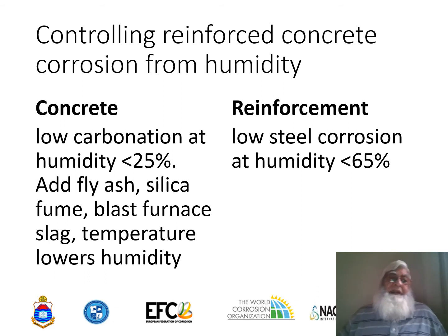Additives are always added, like fly ash, silica fume, and blast furnace slag, and keeping the temperature high will also lower the humidity. For the reinforcements, steel corrosion is in fact possible only when water is there, but it only becomes significant when the relative humidity is less than 60%.